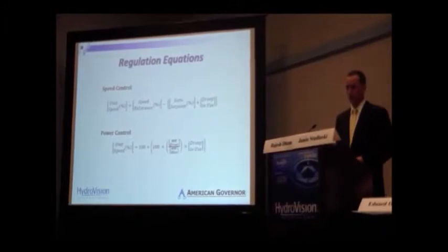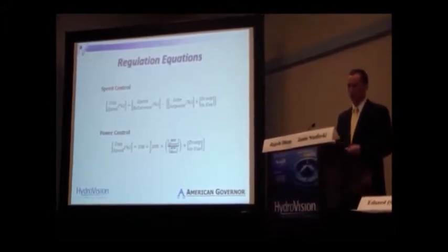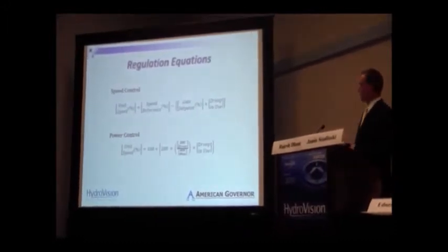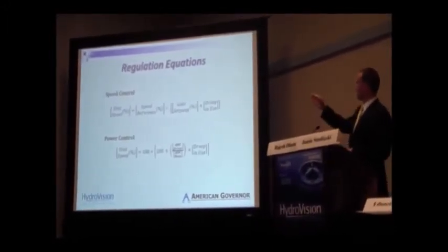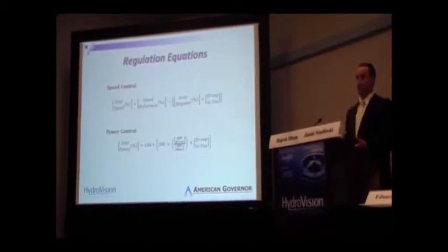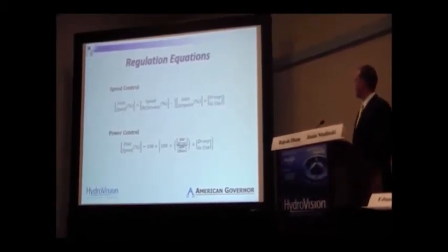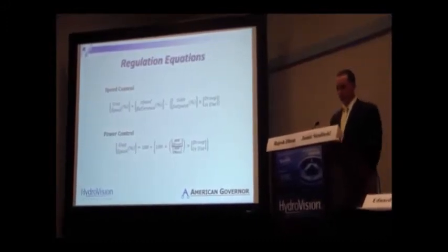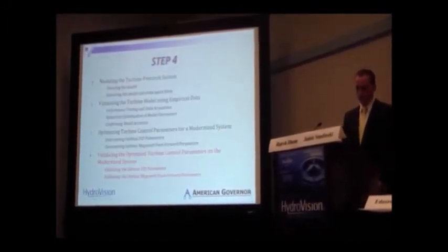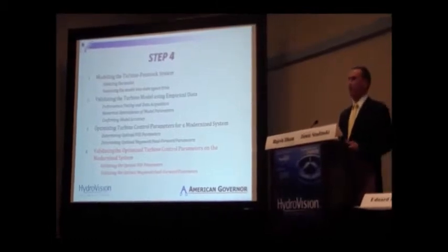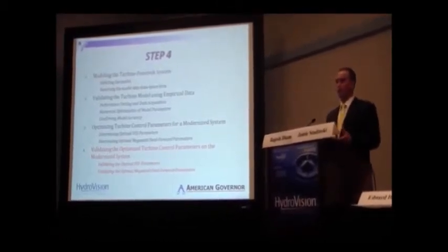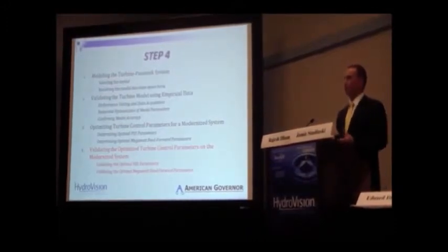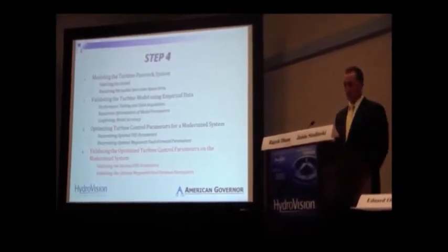And here we're just showing the regulation equations that we use. And in order to get into the system and start messing with things, if we're talking about regulating speed, we have a speed reference that we can adjust virtually and see how the system responds. And in power control mode, there's an inherent megawatt set point which we can adjust and play around with. So really, once we were able to develop that model, we could go in there, play around with the gains, with the settings, and tune our system, tune our virtual power plant before we got to site.